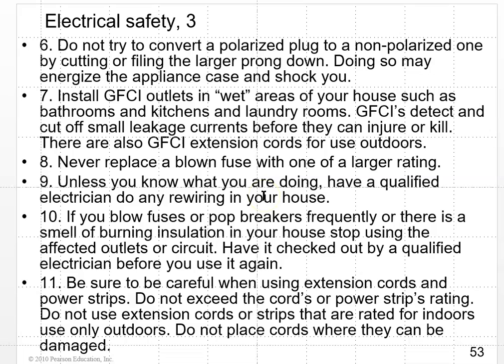Never ever replace a blown fuse with one of a larger rating. Unless you know what you're doing, have a qualified electrician do any rewiring in your house, not Bubba down the street. If you blow fuses or pop breakers frequently, or there's a smell of burning insulation in your house, stop using the affected outlets and circuit. Have it checked out by a qualified electrician before you use it again.